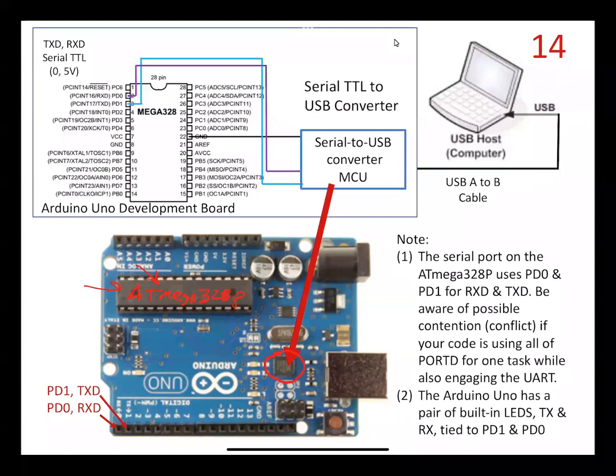And that's why you can take this device, and what it's doing is it's taking these 2 data lines that we just talked about, and it's formatting those and sending them out over USB. That's why you can just take the Arduino and plug it right into the USB port, and it just works, right? Your laptop host knows to talk to it. It sets it up over a certain COM port, and that's all taken care of in this serial to USB converter.